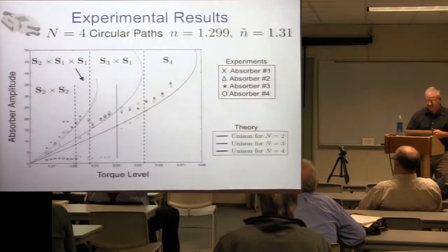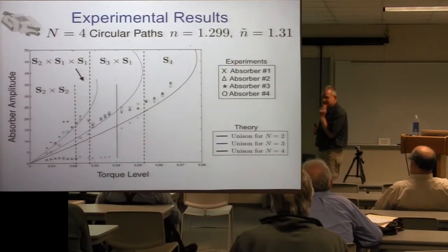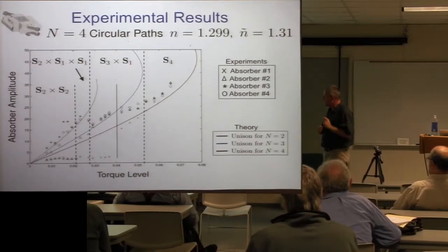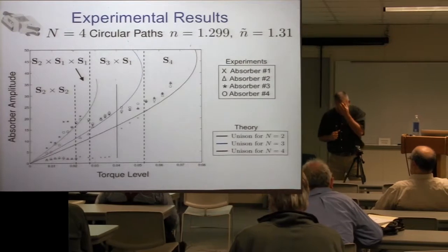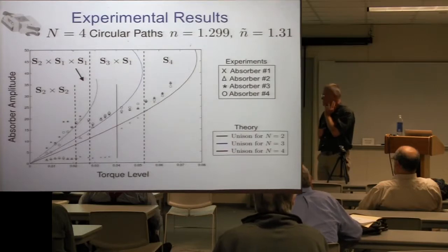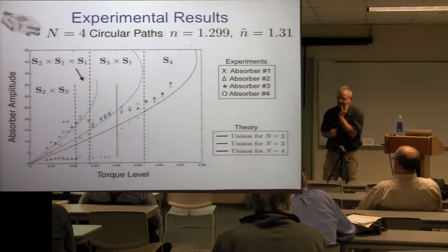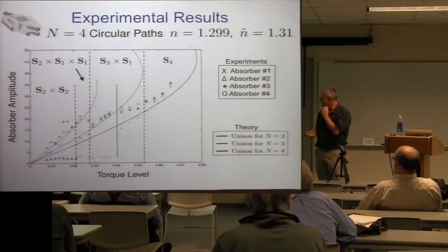So when you simulate that in your model, you don't see that behavior? The only thing that I can say is that probably within machine tolerances, my only guess right now is that the differences in friction and the absorber damping cause this. And we play around with simulations, we put dry friction in, for example, but these are wiggling a little bit, so it's not really dry friction.